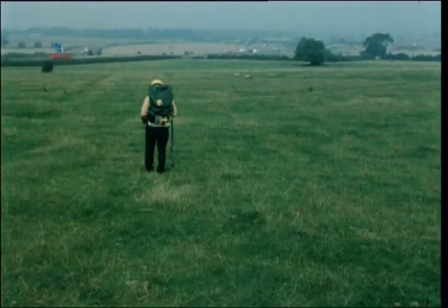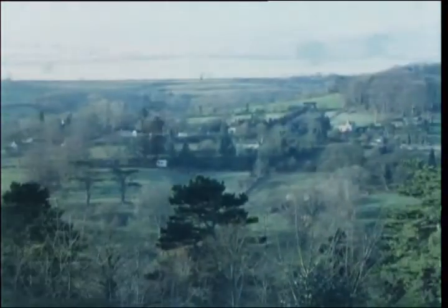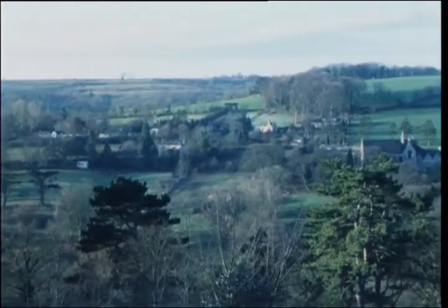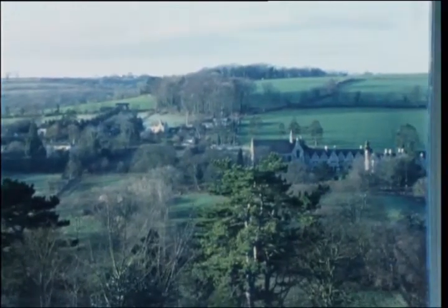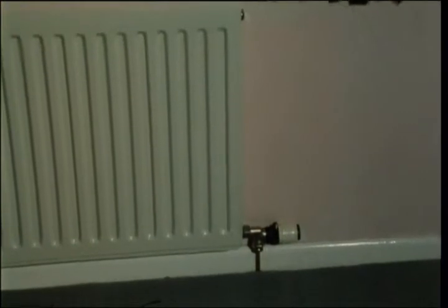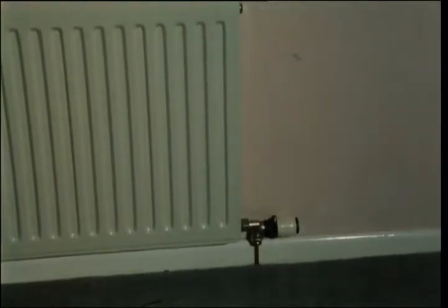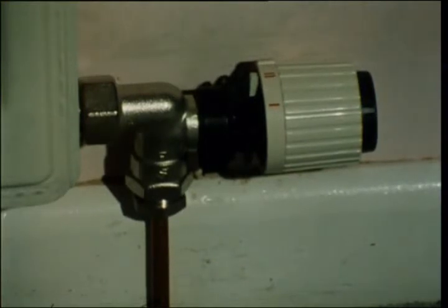For steel to rust, there must be both water and oxygen. But where water is essential, as for heat transfer in central heating systems, rusting is avoided because the initial supply of oxygen in the closed system is quickly used up. And without oxygen, there is no further corrosion.